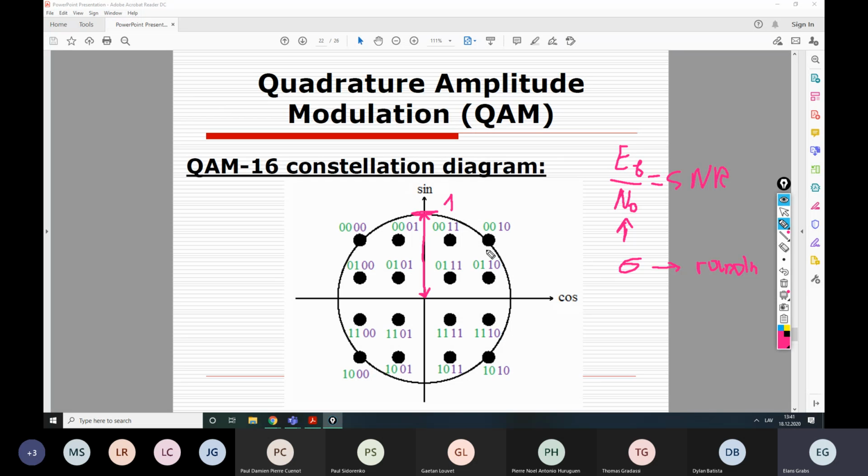Right? So here we need to evaluate the average energy of all these signals, right? So the average energy will be dependent on the total radius, and we assume that this total radius is set to 1. Accordingly, each of these amplitudes needs to be calculated correctly, right? And also, please note that we generate this signal, as I have told you, by setting values from -3 to +3.